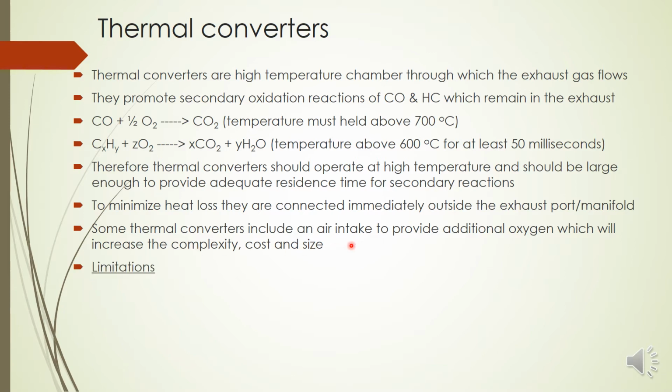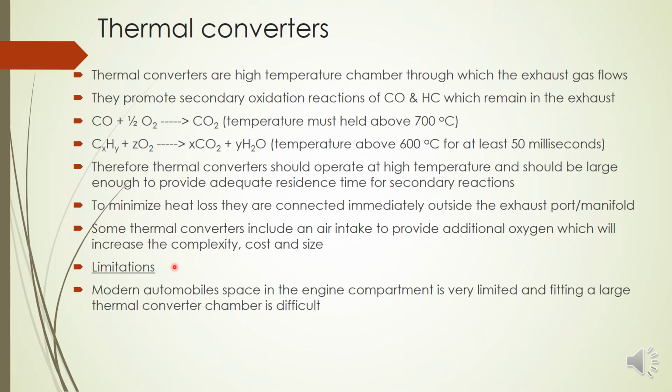Then what are the limitations? Have you any idea what the limitations of these thermal converters are? The first one is that the modern automobile engine is very small and will not have a large space for accommodating this thermal converter, because it is a lengthy chamber. So we may not be able to accommodate this in every engine compartment. That is the first limitation. The size of this will be a problem.